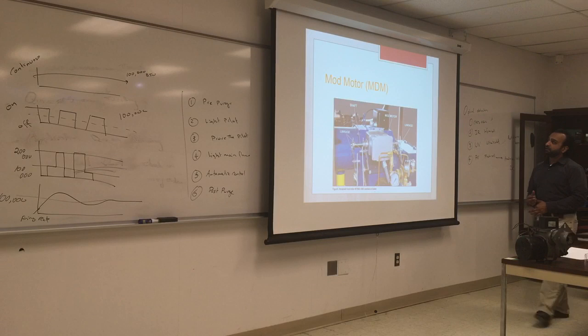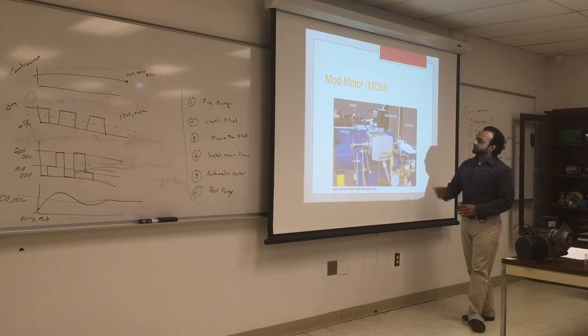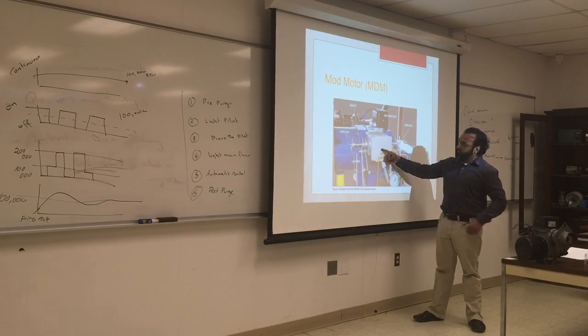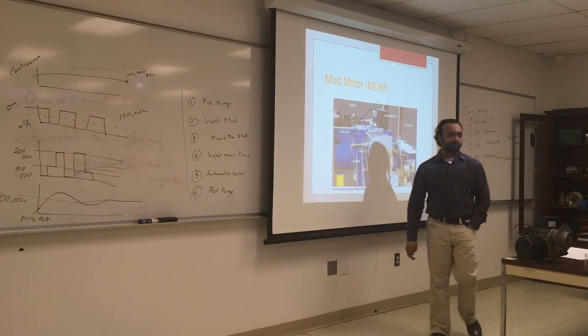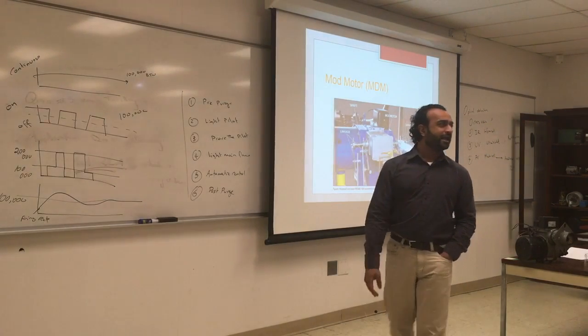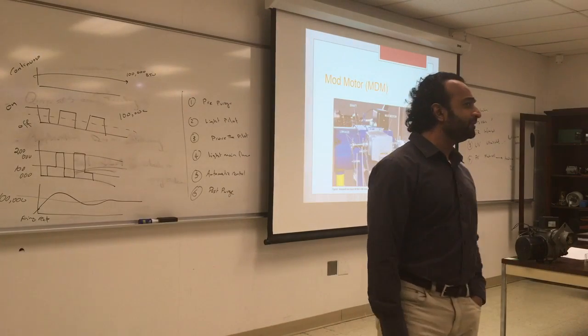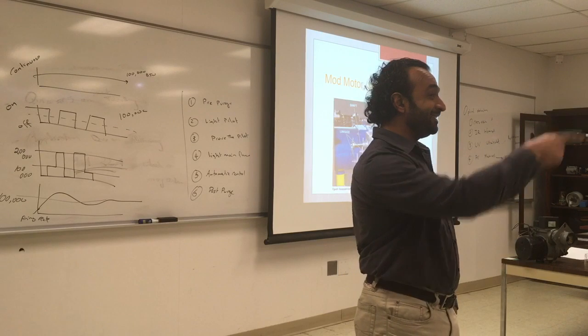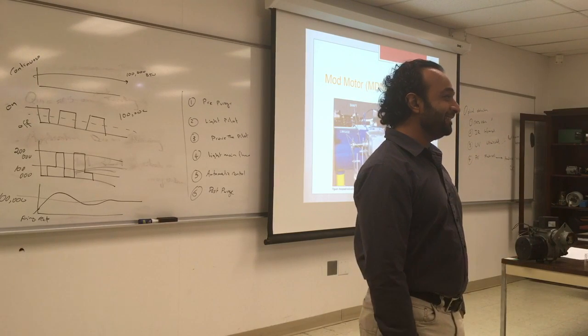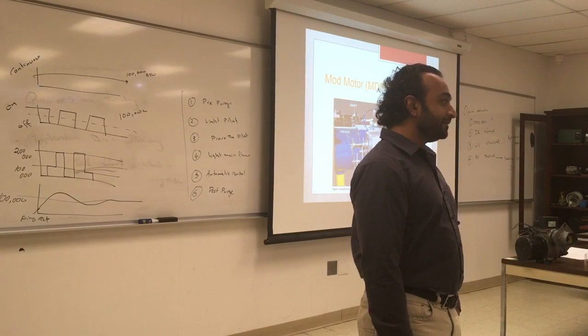So this is called the modulating motor damper. It's a device, basically mechanical. It works with a cam. What's a cam? We all hear about camshaft and cam valve, and double cams, twin cams. Like an egg shaped, or some kind of odd shape that spins on the center of the shaft to give motion to another object.